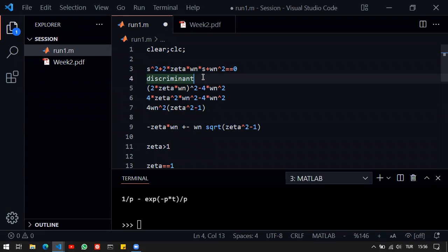And the best way that we can do for now to deal with these other poles and zeros is to push them far away. So we're basically trying to convert all the systems that we will control into second order all pole systems. And this is called dominant pole placement because the dominance of the system, or the behavior that should be dominating in our control strategy, is the second order part.